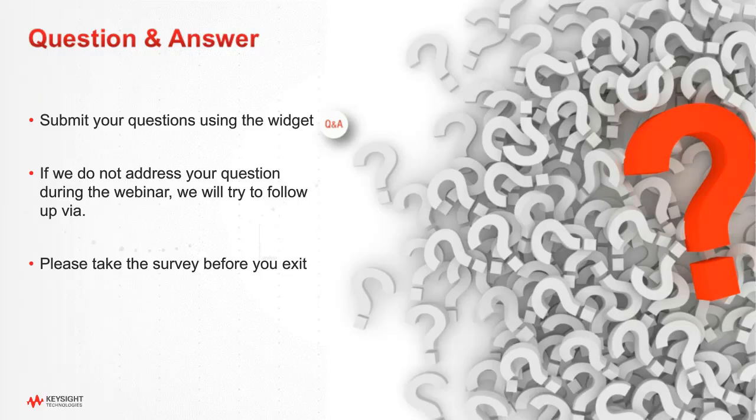It's a great question. The question was, what's the requirement for 4 and 2 channel? The requirements are changing a little bit. As I alluded to earlier, in an earlier version of the CTS, there's a notion of a skew measurement. When you do a skew measurement, you almost have to have a 4-channel scope, because you have to put the plus minus, let's say, into a pair, and the other plus minus into the other side. So there's definitely a requirement to do that.